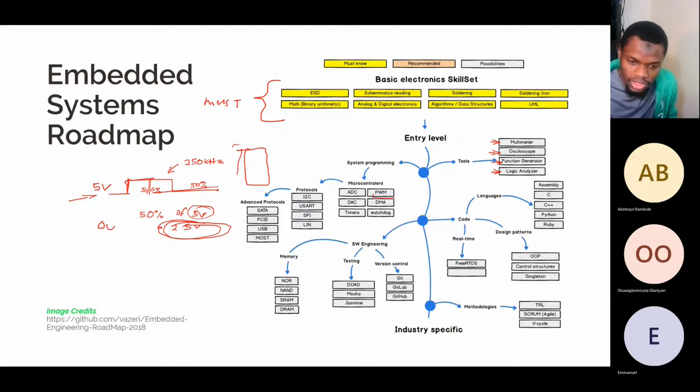The way watchdogs are designed, there are multiple types of watchdogs, right? Some are designed in such a way that every five minutes you send a particular message to your microcontroller, and your microcontroller sends you a response. Depending on what you get as a response, you can tell whether the microcontroller is working the way it's supposed to work or not. Based on that, you can maybe turn off the system to prevent some crazy things from happening. Do you understand? Yes, sir.